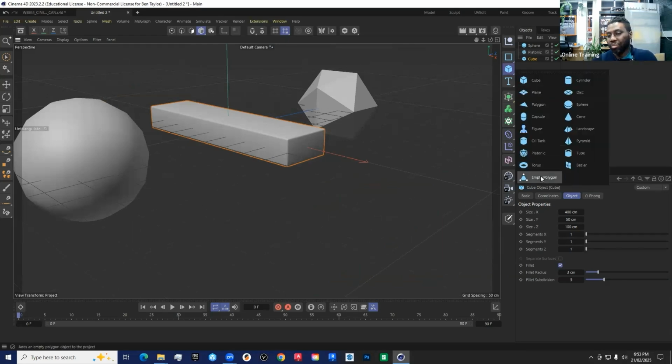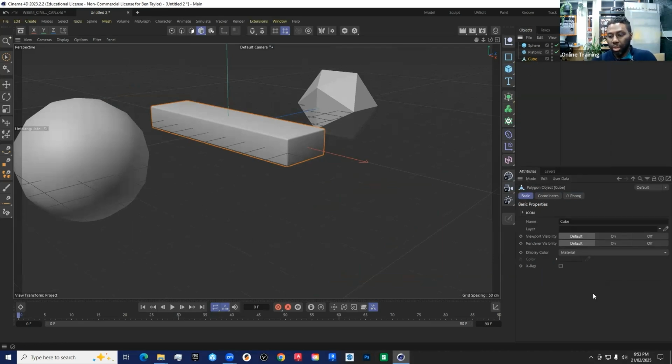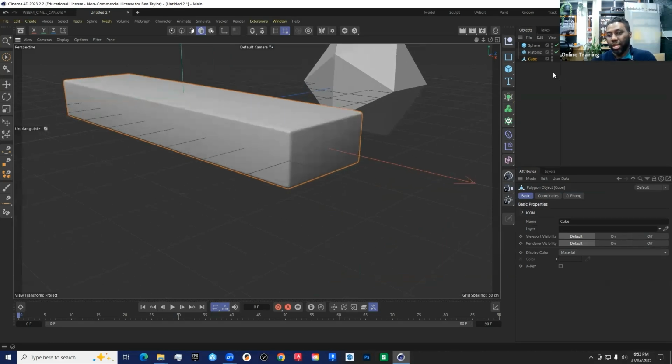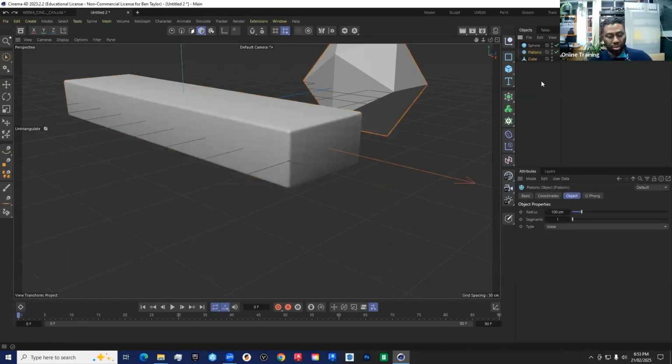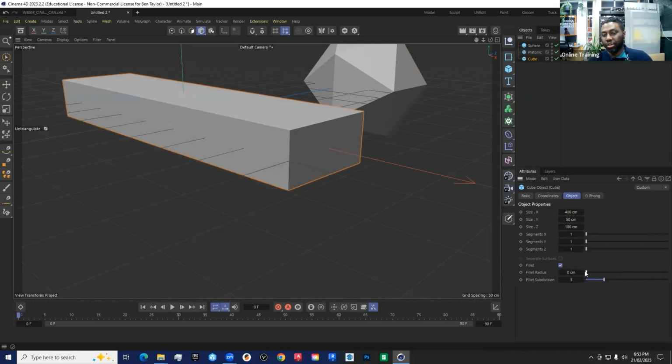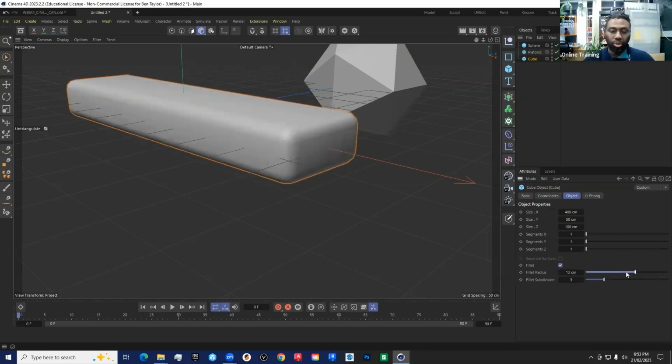If you remember, we saw here an empty polygon, because once we make something an empty polygon, we don't have those parametric controls. It doesn't lose the data we've already given it, but I no longer have the ability to change the size of that curvature. So if I go back a step, and this is a cube again, I can change the size of that fillet while it's parametric. Again, we'll go through all of those different modes, but that's what that does.